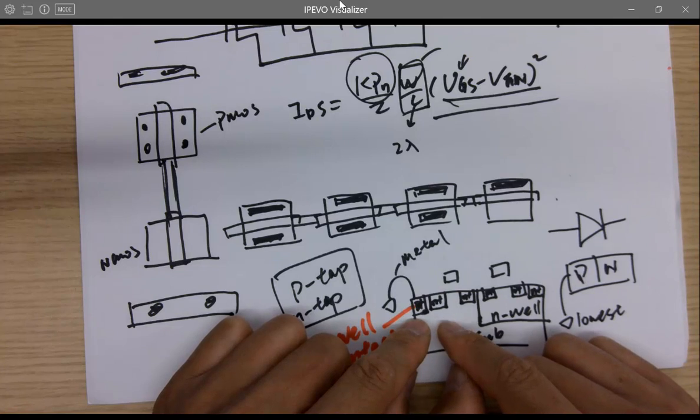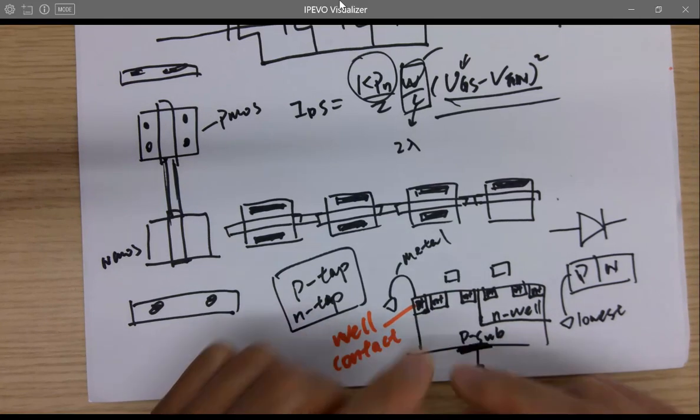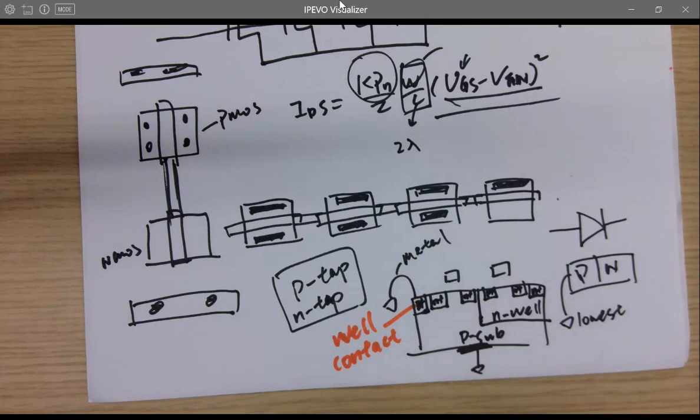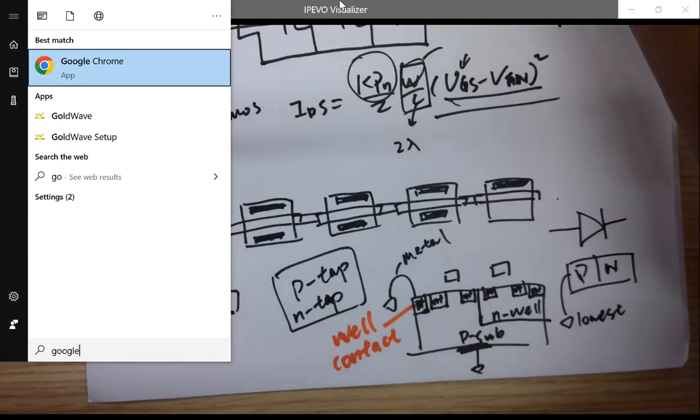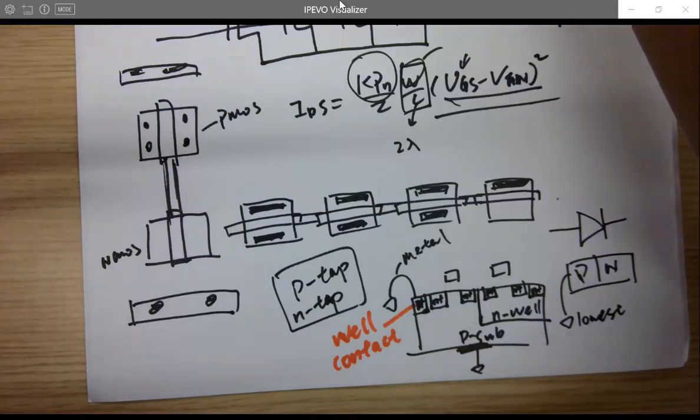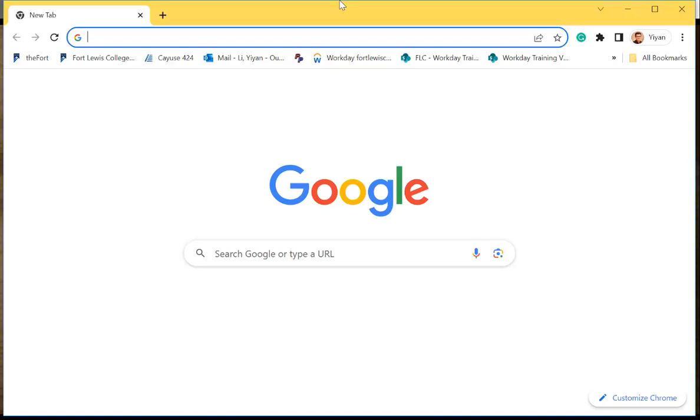But sometimes in the design of the charge pump, we are going to use it for one of the circuits, but we're not going to design it. So we need to place that transistor in a different well. In that case, the way to lay it out is going to be different. But here, it'd be very helpful to explain this now, so they're not getting confused.